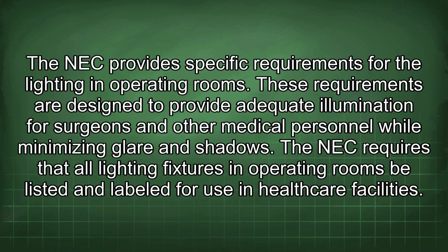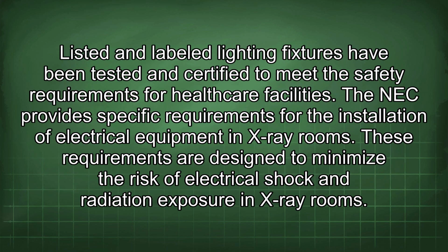The NEC provides specific requirements for the lighting in operating rooms. These requirements are designed to provide adequate illumination for surgeons and other medical personnel while minimizing glare and shadows. The NEC requires that all lighting fixtures in operating rooms be listed and labeled for use in healthcare facilities. Listed and labeled lighting fixtures have been tested and certified to meet the safety requirements for healthcare facilities.